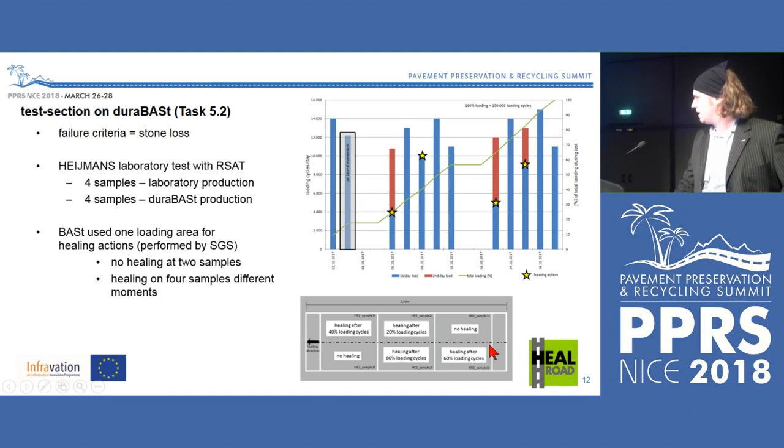This is the 3.5 meter long loading area where we have constant loading with the MLS on the center line, and then we moved 350 millimeters to the left and 350 millimeters to the right. We designed 2 samples with no healing, so there's no maintenance work during the loading process. Then we had different samples after different loading periods.